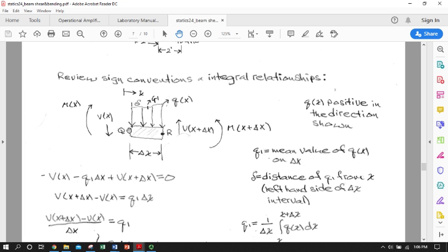So we've taken a section of the beam that's delta x wide. We've hacked off the whole beam to the right, and we've hacked off the whole beam to the left. We've defined 2 points on the faces of the hacked off sections. We've assumed that this remaining section, or in fact the whole beam, had negligible height and negligible breadth in the direction outside of the paper. So it's really only the x direction that matters. And so we've represented the shear and the bending. We're going to discount axial forces for the moment. Those are pretty straightforward. We're more concerned with the shear and bending relationships now.